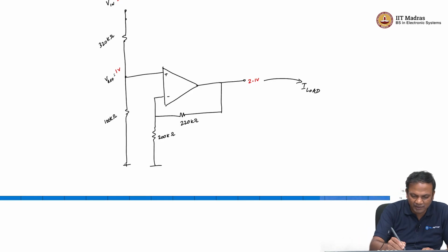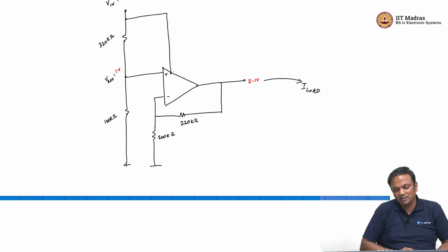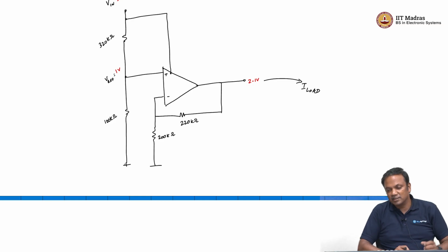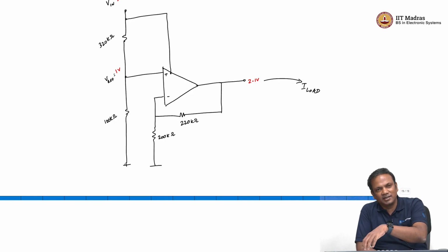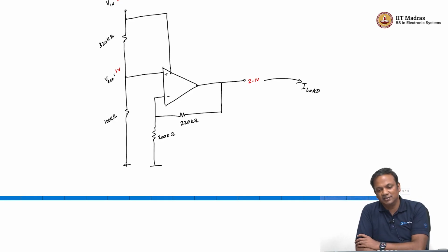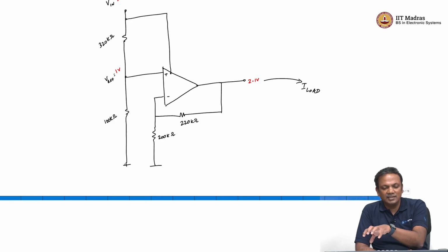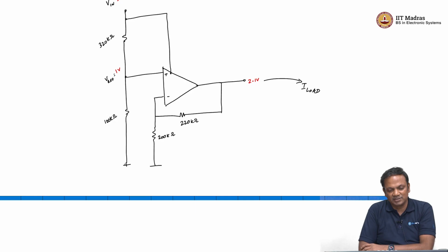One thing I should do for completeness sake is these are active circuits, so they need power. That power also comes from the battery, right. So, it is important to understand here that the change in load current, which is what drives load regulation, when the load current changes, the change in the output voltage is not really related to the 320 kilo ohm and the 100 kilo ohm.